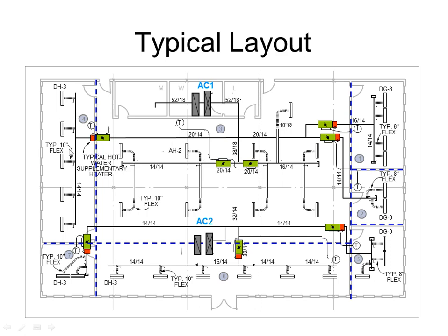So because of that, you would want a supplementary heater so that when the unit is discharging 55-degree air to these zones for cooling, you could reheat that air and provide either ventilation air or heating air depending on what this zone requires, and then vice versa for the afternoon when the sun is on the west side.